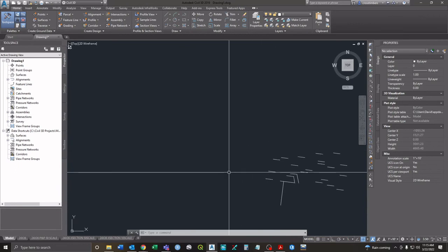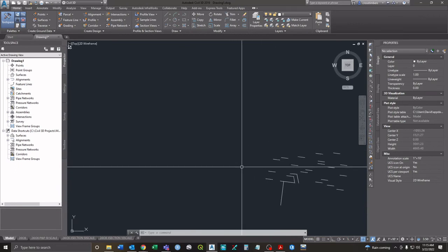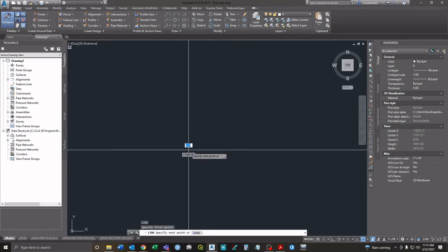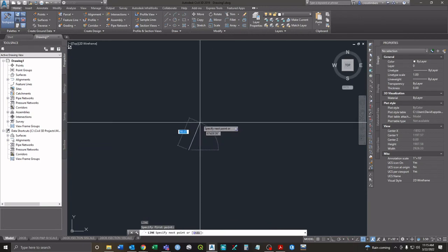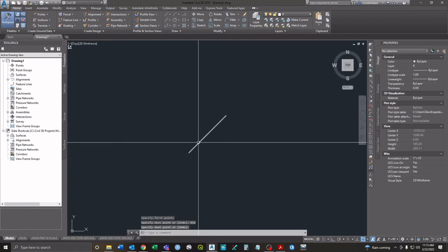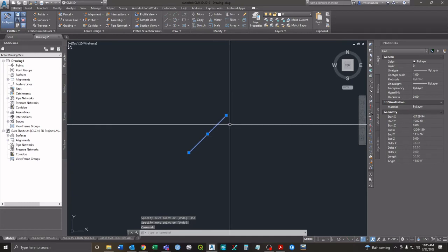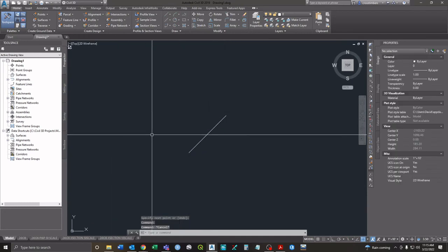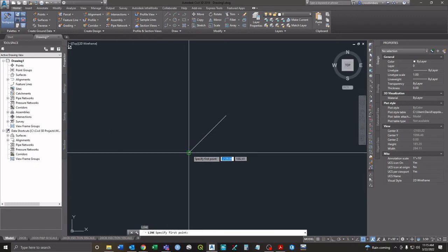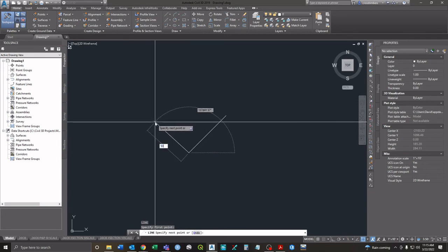So we went through this yesterday, but say you were wanting to draw, so we'll go back to just the line command. Say we started here, and again we have these options. We want a line that's 50, and we hit tab, and then we want it 45 degrees. Enter. So we have a line that's 50 long and 45 degrees. Again, let's say we want to put that same 45 over here. So we either have to remember that a 45 this way is 50 tab at 135,